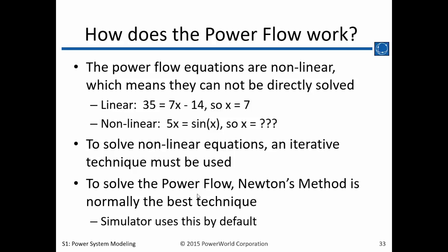There are some other methods out there that you can try to use. You can use a decoupled power flow. Simulator does include a decoupled power flow if you want to try it. It's typically not as accurate as Newton's method, but might be a little more forgiving in some situations. There are things like the Gauss-Seidel method, which is a lot more forgiving to your starting conditions.